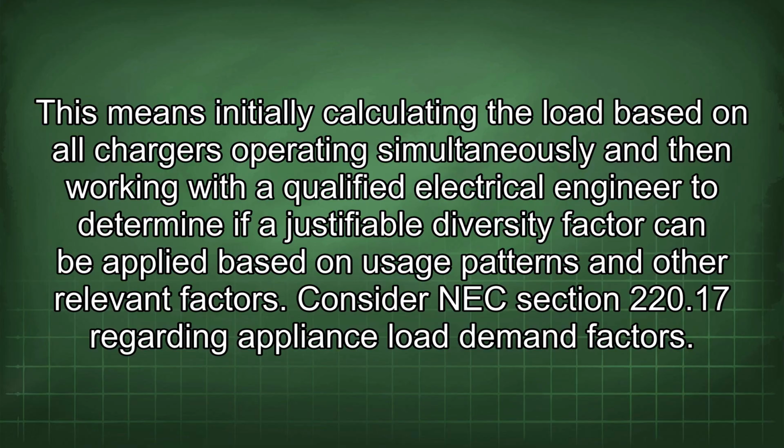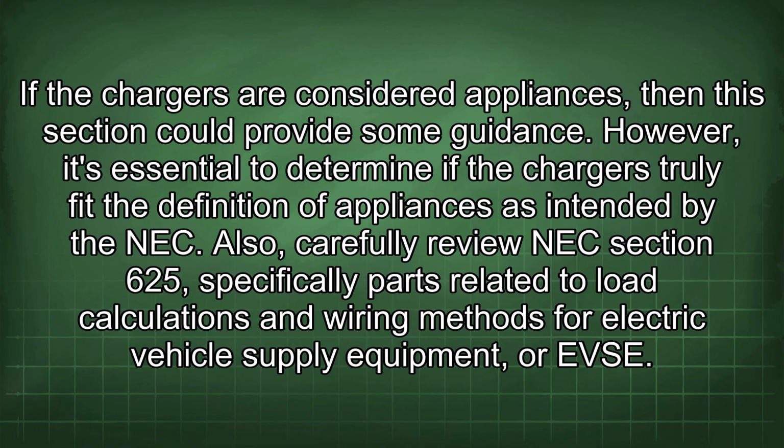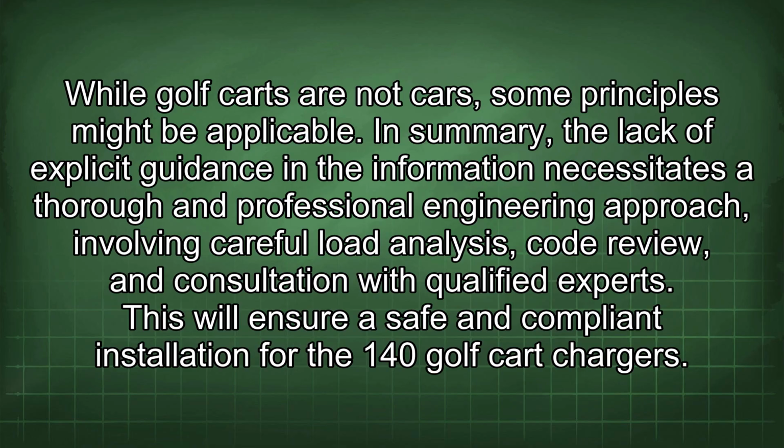Consider NEC Section 220.17 regarding appliance load demand factors. If the chargers are considered appliances, then this section could provide some guidance. However, it's essential to determine if the chargers truly fit the definition of appliances as intended by the NEC. Also, carefully review NEC Section 625, specifically parts related to load calculations and wiring methods for electric vehicle supply equipment (EVSE). While golf carts are not cars, some principles might be applicable.